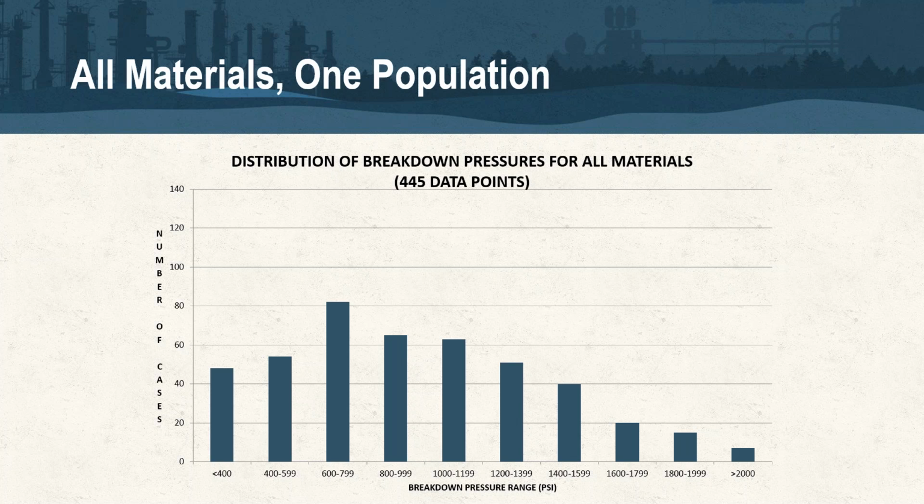and permeability. And what we typically target when we do an injection is initiating a freshwater test on those intervals. Where we assess a go or no go on that specific interval is initiating fresh water. If we reach that upper limit of about 1,200 to 1,400 PSI and nothing happens, it just holds, that particular interval is believed to be non-producing and non-effective for the purpose of injecting a slurry.